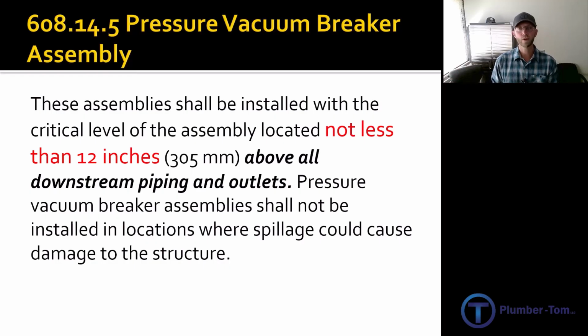When a backflow situation happens, vacuum breakers just dump. They make quite a mess. They're great for use outside. They can be used in mechanical rooms with floor drains, but you don't want them somewhere it's going to be damaging cabinets or flooring or anything else.